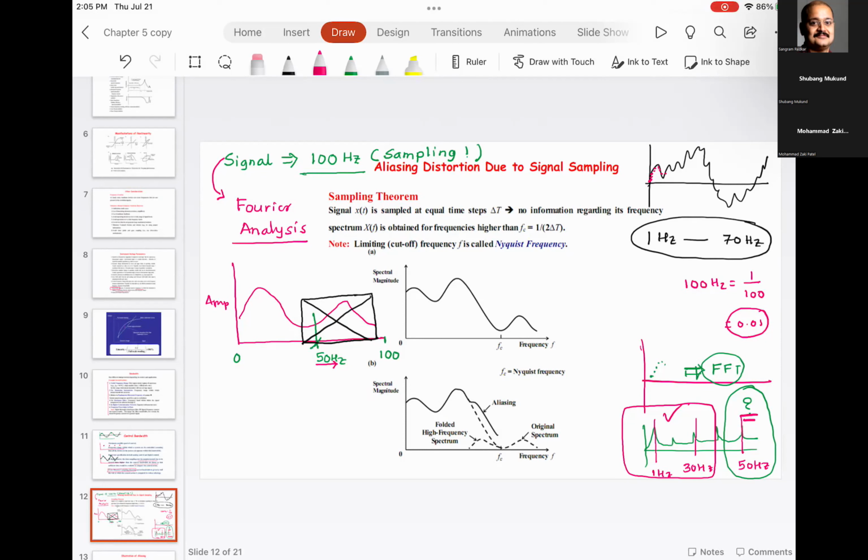There is nothing in there that operates at 80 Hertz. So what do we do? There is nothing in there that operates at 40 Hertz. What do we do? Then the whole issue got resolved when we got an accelerometer which could sample at 1000 Hertz. And then we sampled the data at 1000 Hertz. We did the FFT, and at that time, we could see that, yeah, this is where the problem was.